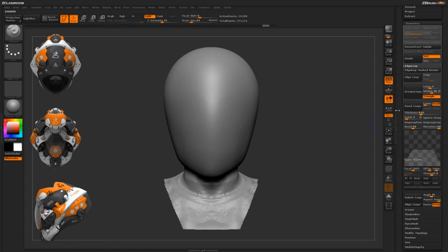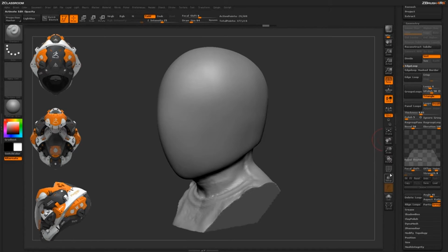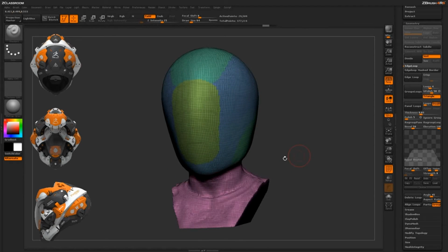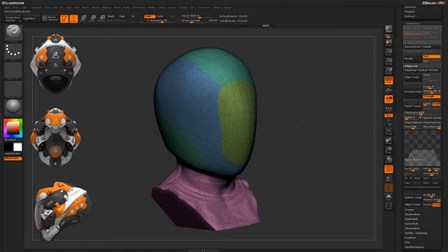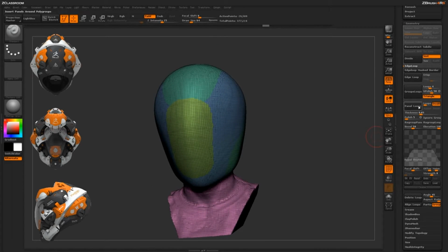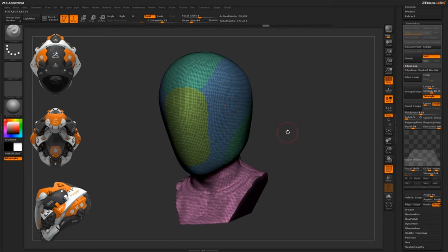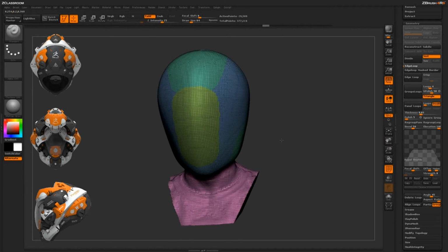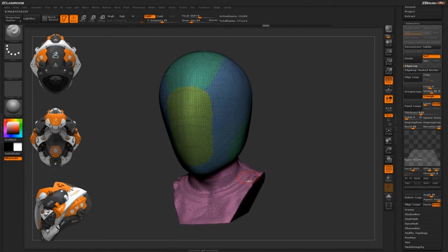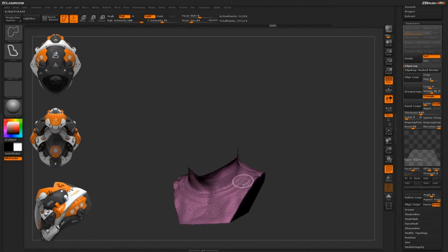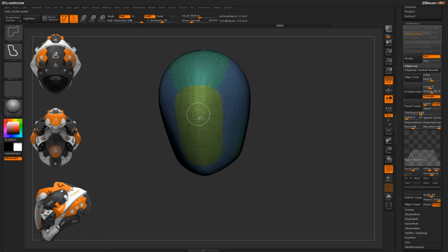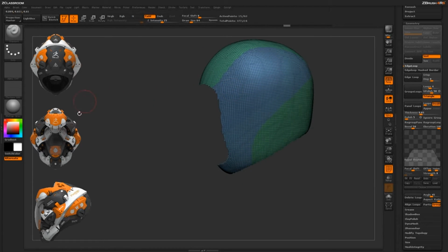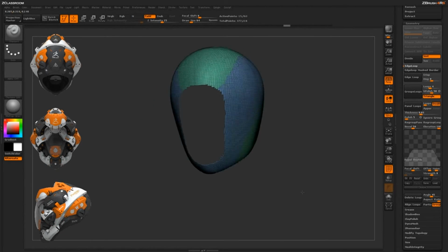Well, there's a few areas on this model I don't really want panel group loops generated. So I don't really want this neck area generated, and I can just generate the visor later on, so I'll probably just remove this one as well. So the panel loops functionality has an option to only generate panel loops on the areas of your model that are visible as well. So if I come through and just hold Control Shift and then click the body, and then Control-Shift click again, which will make it hidden. I can then Control-Shift click that visor, and now I'm just left with those core elements of the actual helmet.